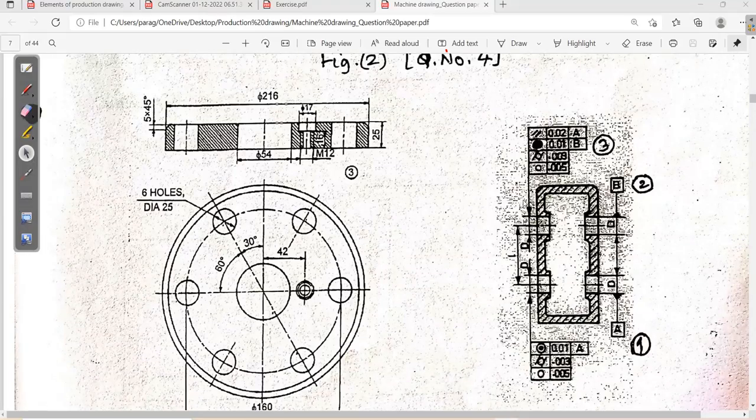Okay, now this is the question. So bottom face, this is the jig. Now bottom face has to be indicated by datum A. So how do you represent a datum? Okay, a straight line along with that box and closed triangle. Here there is a triangle at its foot, and in that we write the symbol, datum A. Okay, so this was the first question. Right? Now next.